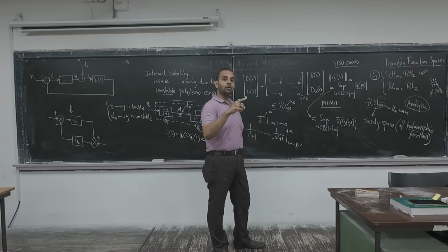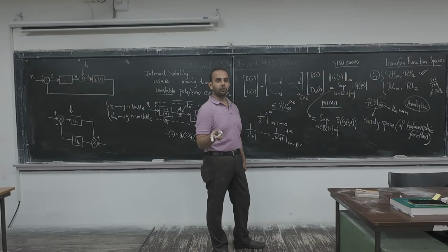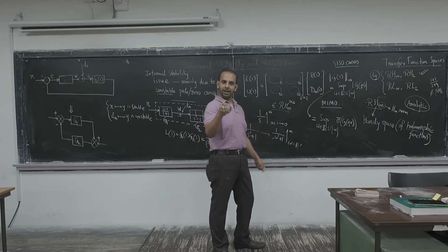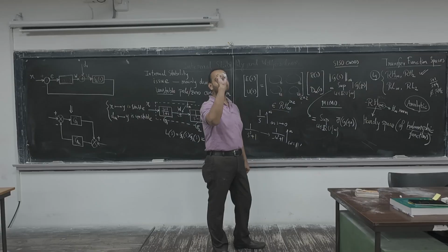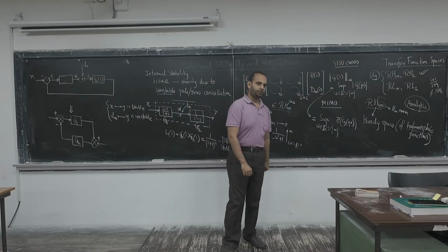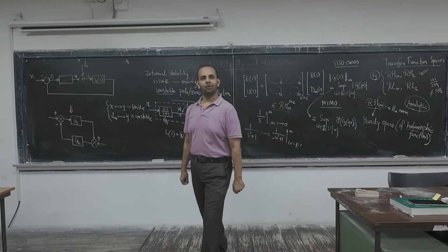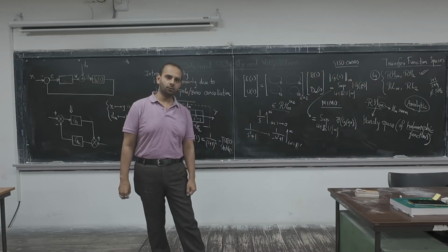Why? Mostly because of the Bode plot. To all control students, the Bode plot and frequency response are quite well known. So anyone can talk about the H infinity norm, because at least in SISO cases, the H infinity norm means the maximum frequency domain gain. Whenever we talk about the gain of a system, that is a frequency domain gain, right?